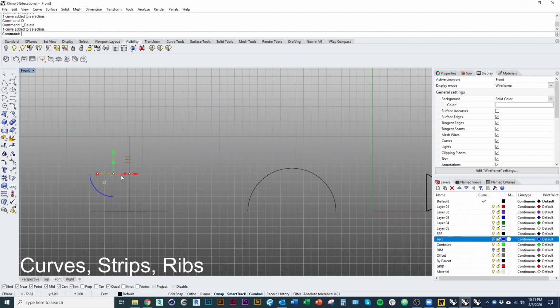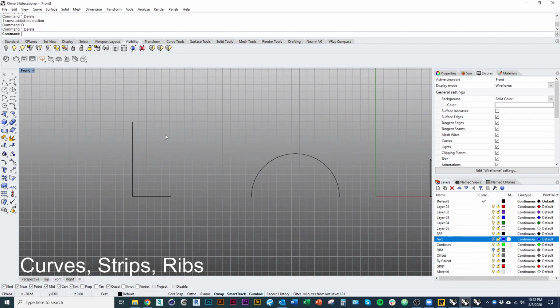The other thing you can do, which is a little simpler, is instead of drawing it as one symmetrical arch like that, you can draw it based on tangents. So if I use the same command, interp curve, right here in my options I have this button, Start Tangent, and I can click on that. I've selected the point where my curve is going to start, and then in order to set the tangent, or basically the direction that my curve is going to be going at that point, I'm going to click on the button Direction. And I'm holding shift and clicking up like that. Now you can see wherever I go, my curve is going to start by drawing in that direction.